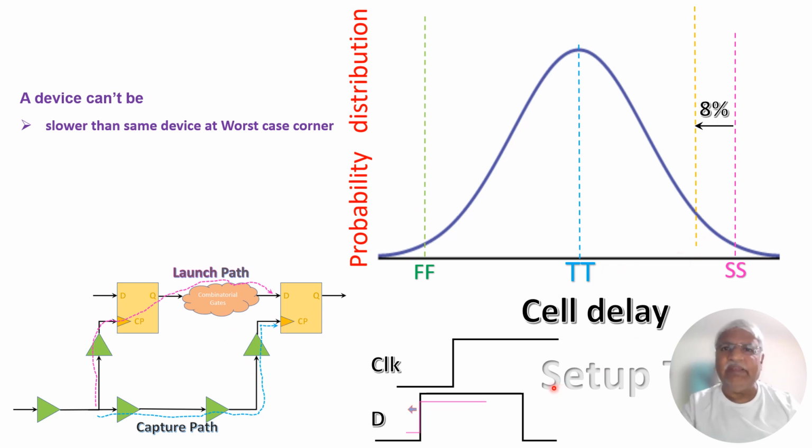When that happens, the data comes early, so now we are creating a pessimistic scenario. We can ensure this with this much derate. This value differs from technology to technology and scenario to scenario; if the nominal condition or the temperature changes, these things also change. Currently we are not talking about VT variation and other variations.